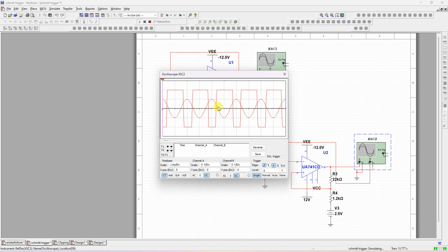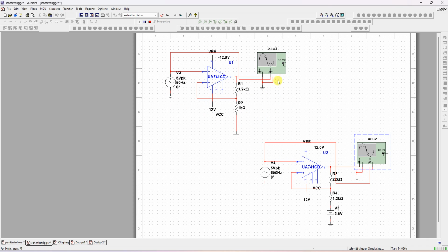Getting both positive only. Okay, if you want different, I think this is plus 2 and plus 4. Okay, plus 2 plus 4, UTP 4, LTP 2. So for this also I will change this one, instead of 500 hertz, to 50 hertz.